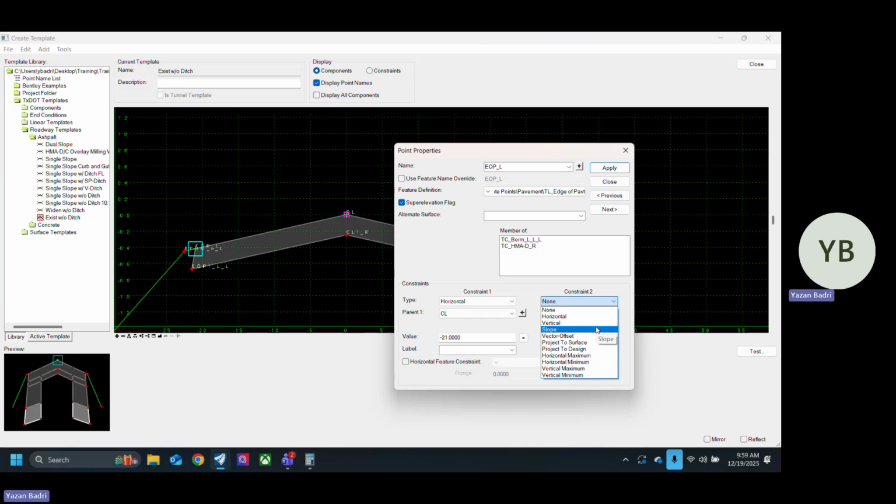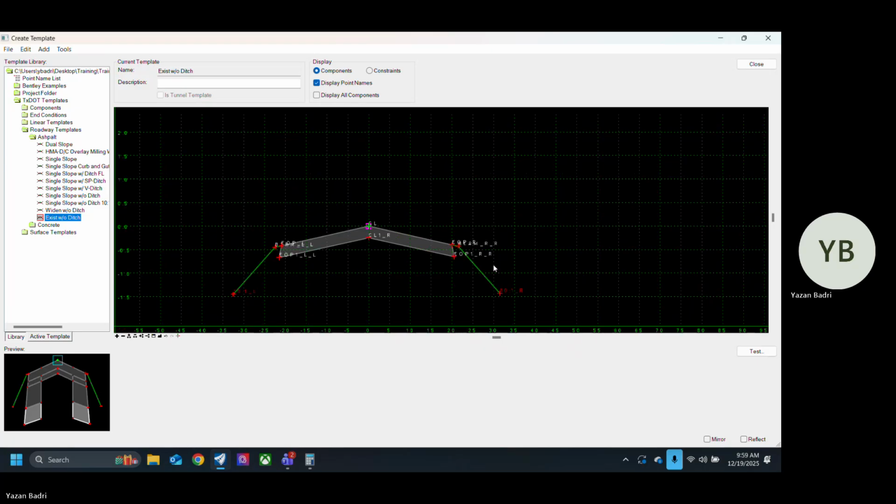Wait, I'm confused. Isn't the taper also gonna be not... What taper? Because we did it at the cross culvert, and then won't it do the same? No, imagine outside the culvert area. How's the section gonna look like? Just an overlay, right? Well, it can't be, because what she's saying is they're building the full width pavement at the culvert, and then they're gonna taper it back down to existing, so at some point, it's gonna go from 8 foot, 7 foot, 6 foot, 5 foot. Yeah, no, I understand.